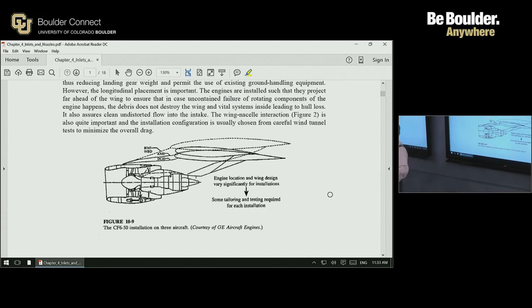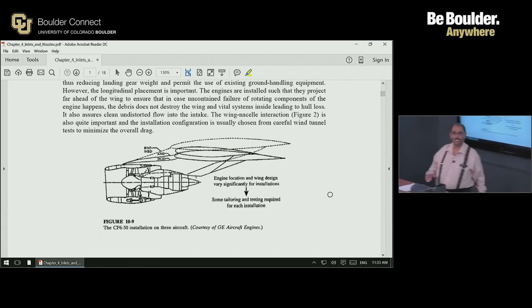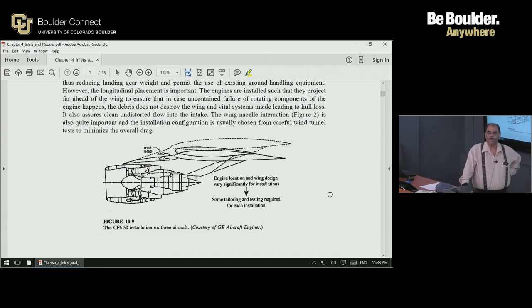That is simply because the 1950s design of the landing gear accommodated only small diameter engines, because the 737 was essentially designed at that time. Turbojets and very low bypass ratio turbofans were the engines that drove those aircraft in those days, and those were more like cigar-shaped engines.